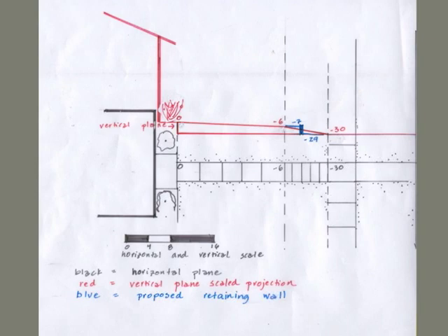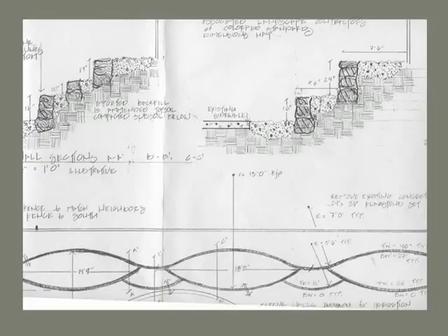And then we plot it on a section view, which is a profile, which helps us determine that in this case, the top of wall is -7, the bottom of wall is -29, so that's a 22-inch high wall. And we plot over a course of a bunch of different areas in our walls, and we get really accurately designed walls. So here's an old drawing, over 10 years, because we've been drawing on CAD for a long time.